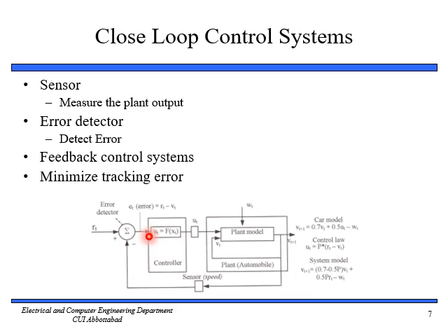A control system with these parts is known as closed loop. It is known as closed loop because our loop starts from here and goes back from output to input again. We can call this feedback or closed loop system. A closed loop system monitors the error between the plant output and the reference input. So what happens on the basis of this error?